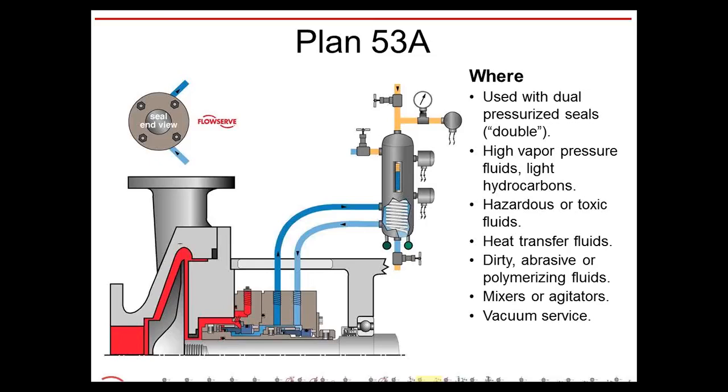One thing to note here is because you are consuming barrier fluid, they make a lot of options now where you can actually fill the seal pot while it's online. While it's under pressure, all you really have to do is pump it in to the seal chamber above what the seal chamber pressure is set at. So it's very easy, and it can be done online. Sometimes they're very simple quick connects that they can put on and fill the system.